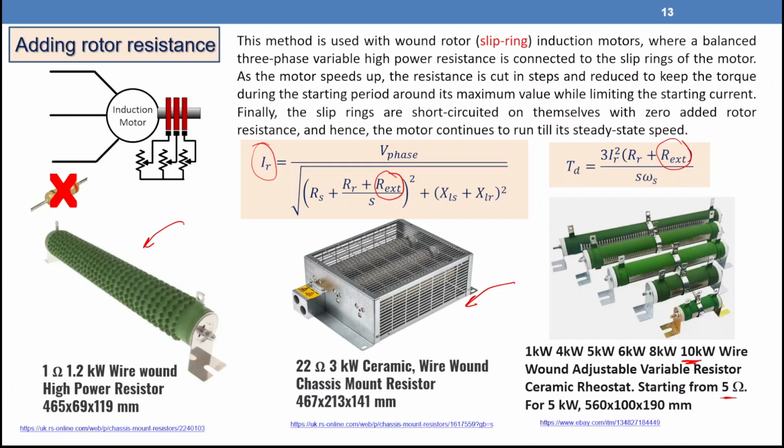We can find another solution. Two reasons here. The size of the resistance, when you are going to put it in a box, will be bigger than the machine. And also if any fault happens, the machine is going to run in unbalanced mode. So that one is not a recommended solution, besides the losses we are going to have in this one.